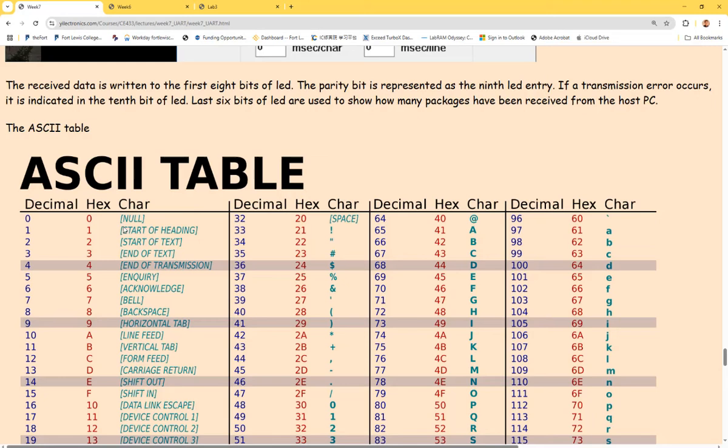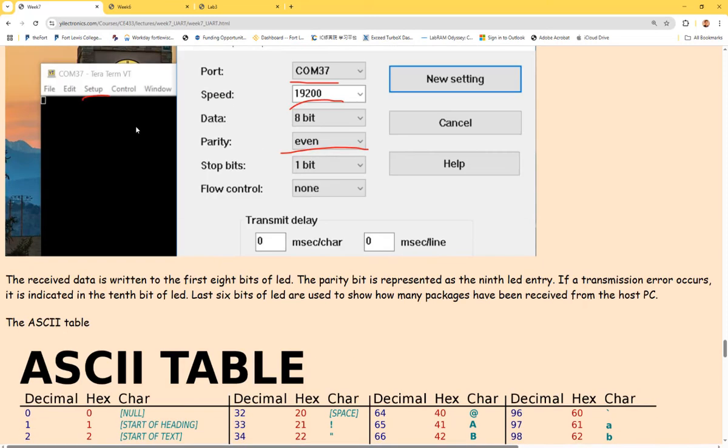And the second experiment is on the receiving mode. So the FPGA is receiving instead of transmitting. Receiving things from the laptop, you press the keyboard keys and send ASCII code to the FPGA board. It's receiving and trying to display. It doesn't have any other display mechanism, so it has to be the LEDs. You can make it more complicated, you can use a 7-segment display, but you don't have to. Just LEDs. So it's bi-directional.